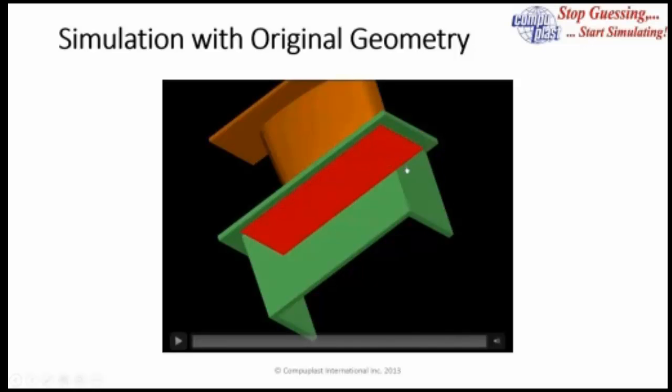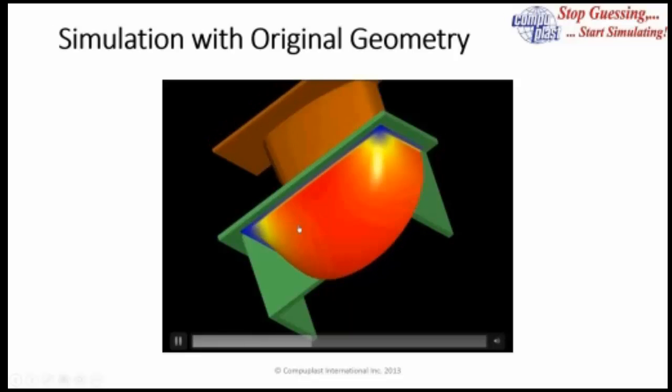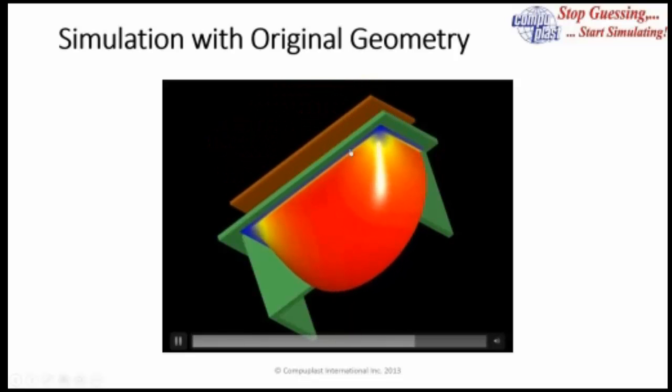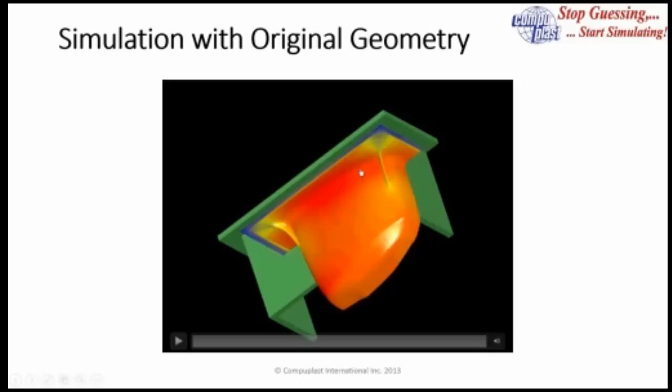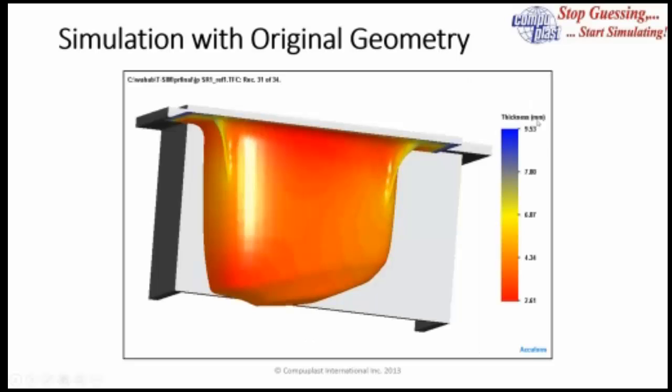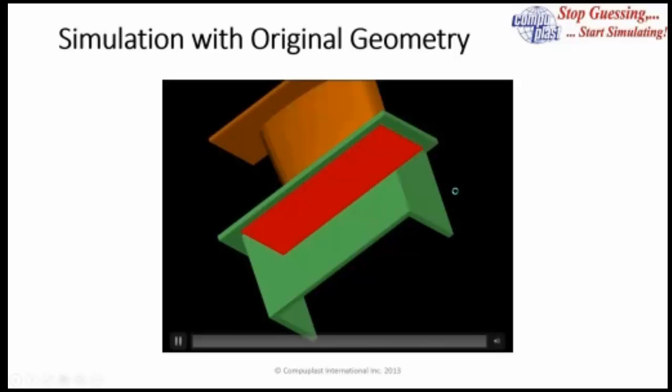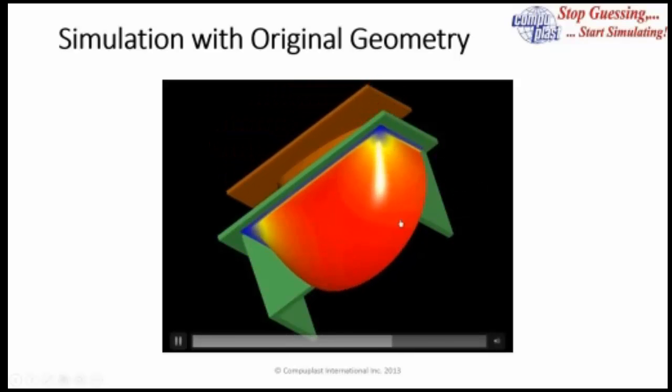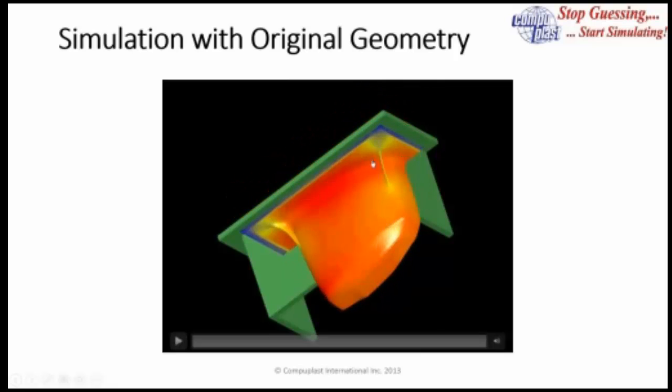So here's the process in action. When we start, we pull a vacuum and draw the material into the box, insert our mold, and then turn the vacuum around and pull the material up against the mold. But as you can see here, and I'll just play that one more time, hang on. As you can see here, we're creating this large surface, and then when we turn around to pull that onto the mold, we create these webs in these corners.